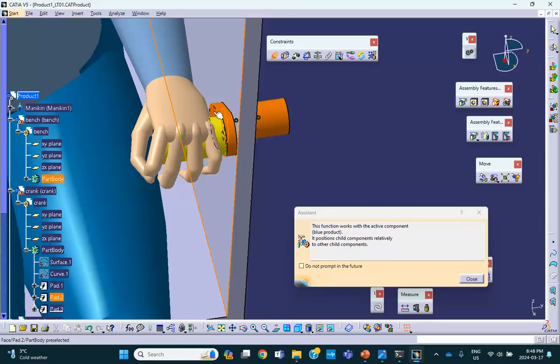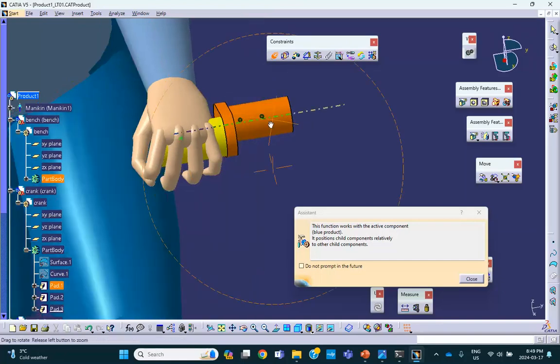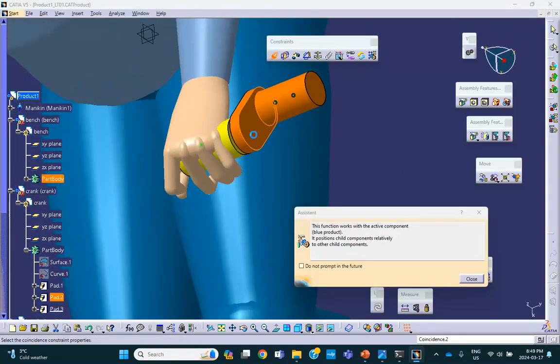So I can select this gray piece that I have already done, and the back of this orange piece over there, or the top of the orange piece, and that becomes a revolute joint with an offset. Whatever is convenient. So let me hide this thing. Is that better? Okay.